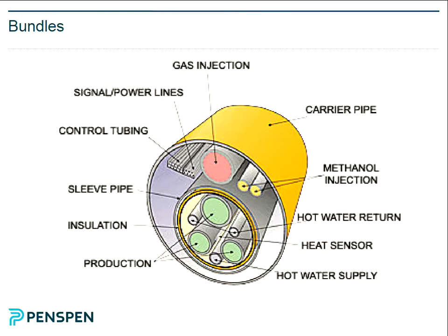Any more questions on the bundle? The pipes are made of different pipeline material, and if that's the case, do you have galvanic corrosion? Yeah, that is a consideration, definitely. Normally you try and make them carbon steel because that's the cheapest, but sometimes they are stainless steel, yes. And then you have to basically join carbon steel to the end. The end bulkhead is a very complicated thing, as you can imagine.